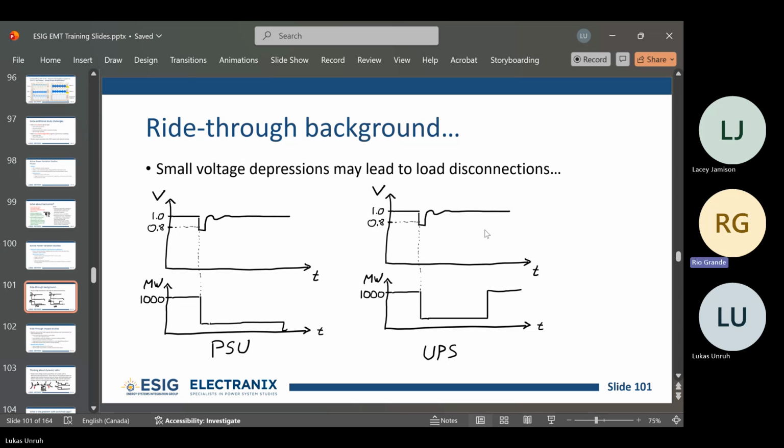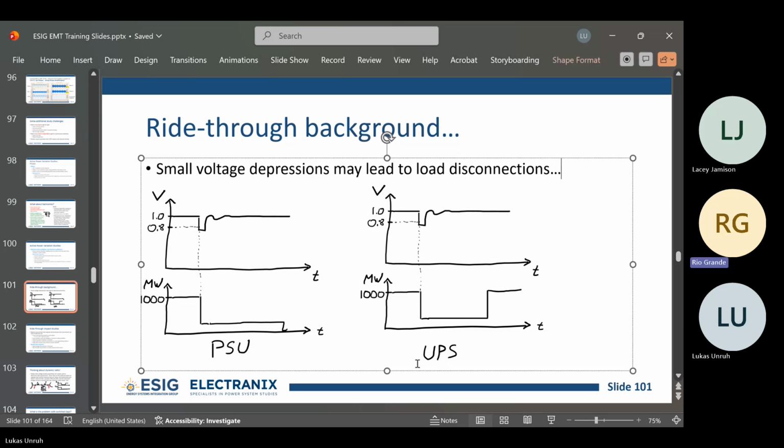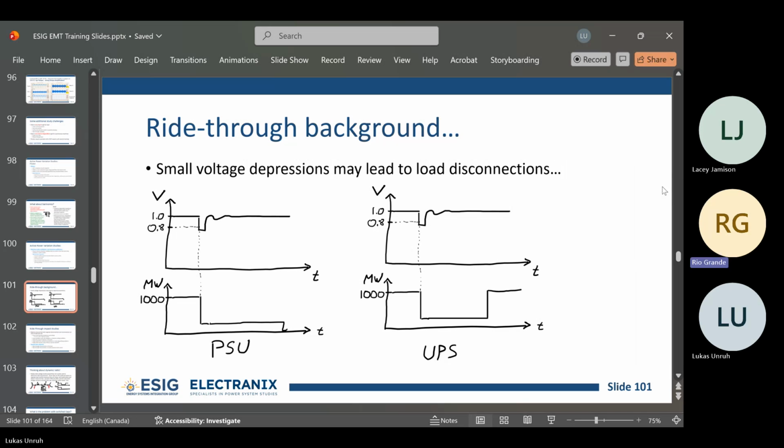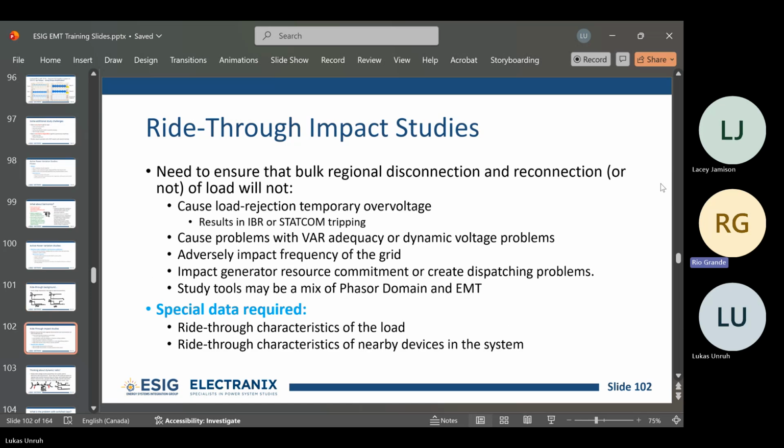And this, it can come back at different time frames. We don't know necessarily how fast it's going to come back after it goes to UPS, but this is something that they could probably tell you. And maybe they can come back, let's say it goes on to UPS, and then if the voltage looks really good shortly after, they might be able to bring it back pretty quick, maybe on a ramp rate or maybe all at once, kind of depending what the system needs. So that is somewhat configurable inside the UPS.